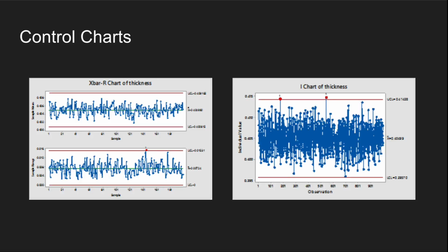If a product is to meet or exceed customer expectations, generally it should be produced by a process that is stable or repeatable. More precisely, the process must be capable of operating with little variability around the target or nominal dimensions of the product's quality characteristics. Using the control chart, we can express the process stability variance from one instance to the next. It can be concluded from this data that the process remains stable after 1,000 instances to stay within the customer's specification limits of target of 0.405 inches with an LSL of 0.395 inches and USL of 0.415 inches.